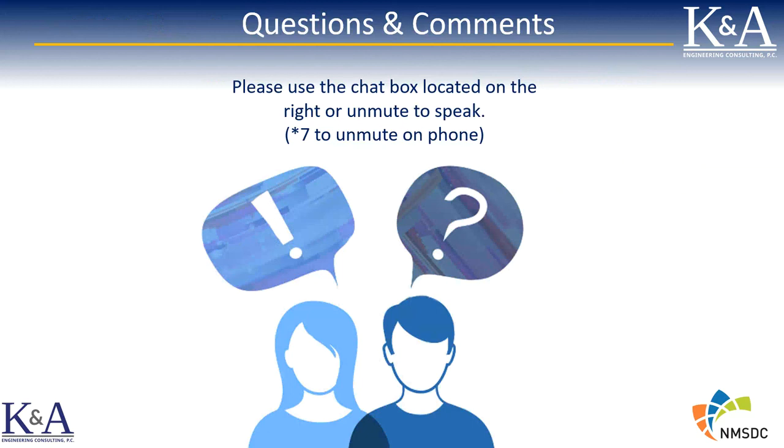Another question for you. How should we protect those electronics in digital substation from EMP events? Yes, EMP events. It's not easy to do that retroactively. It's much easier to design a new greenfield system that's EMP protected. There are technologies out there to do that. Using fiber optic networks is one of the primary ways to do it.